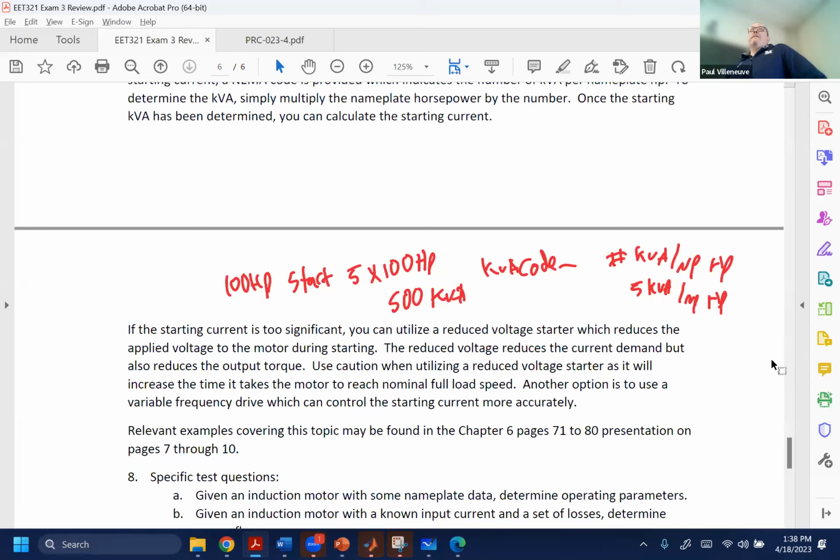It's pretty good stuff. But oil can't work on a motor, right? Why? Because it's got to spin. Doesn't work so well when you have oil in there spinning around with centrifugal force. Eventually it would move away from the winding, so it's just not practical. For the stator windings, you could have oil, but I've never seen a motor that has oil around the stator windings. They may exist, I haven't seen them.